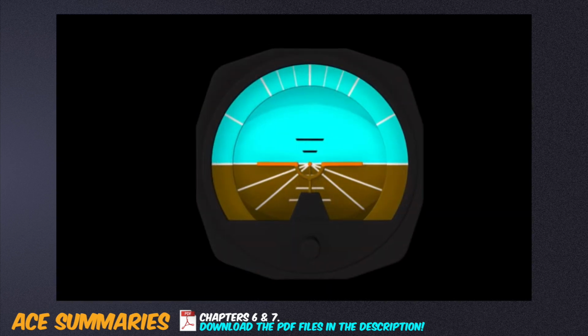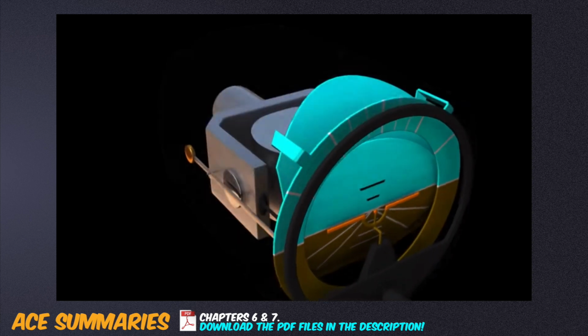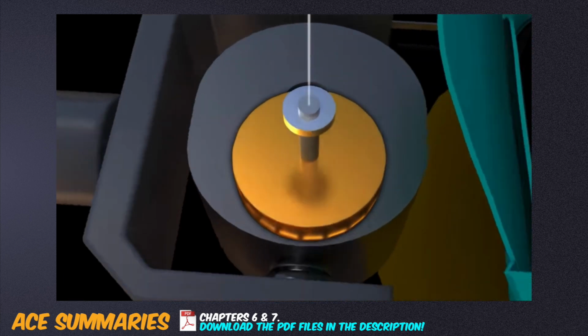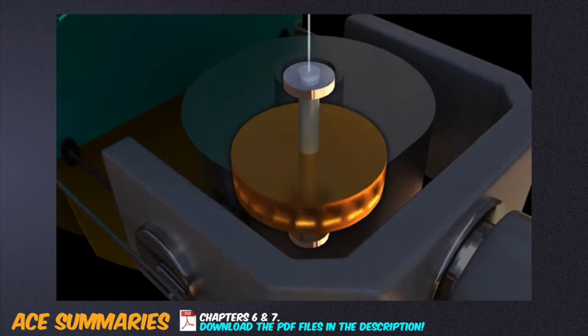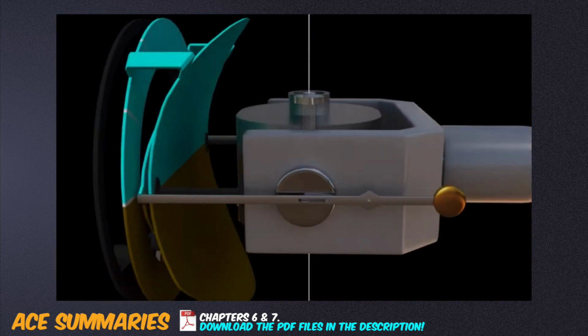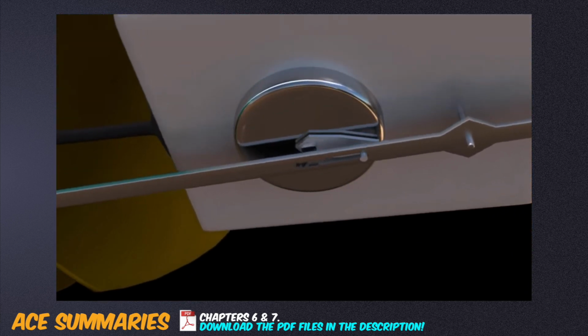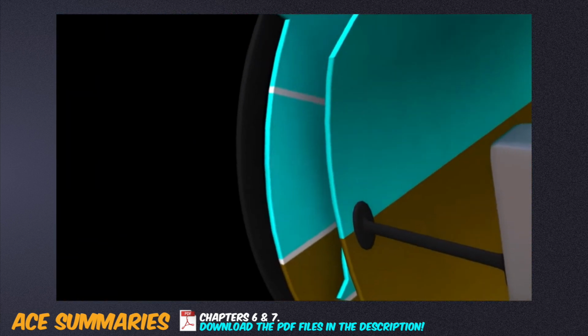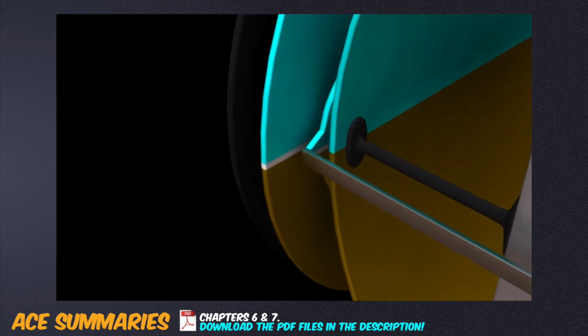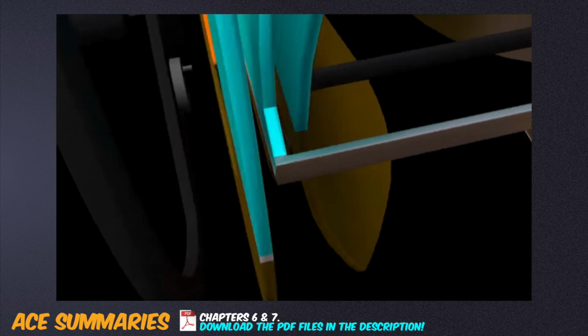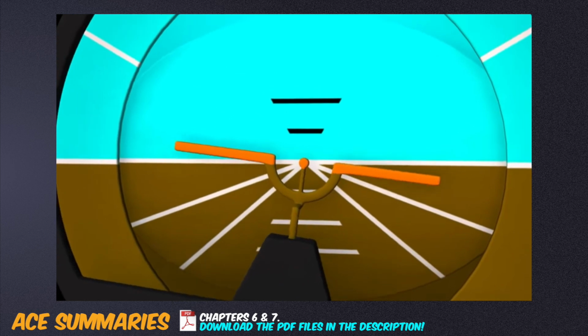The artificial horizon has a gyroscope oriented with a vertical spin axis. It has 3 planes of freedom, spin axis plus 2 gimbal axes. The gyroscope stays aligned with the rotor parallel to the surface. Gimbals measure pitch and roll respectively. There are turning, acceleration, and spin axis wander.